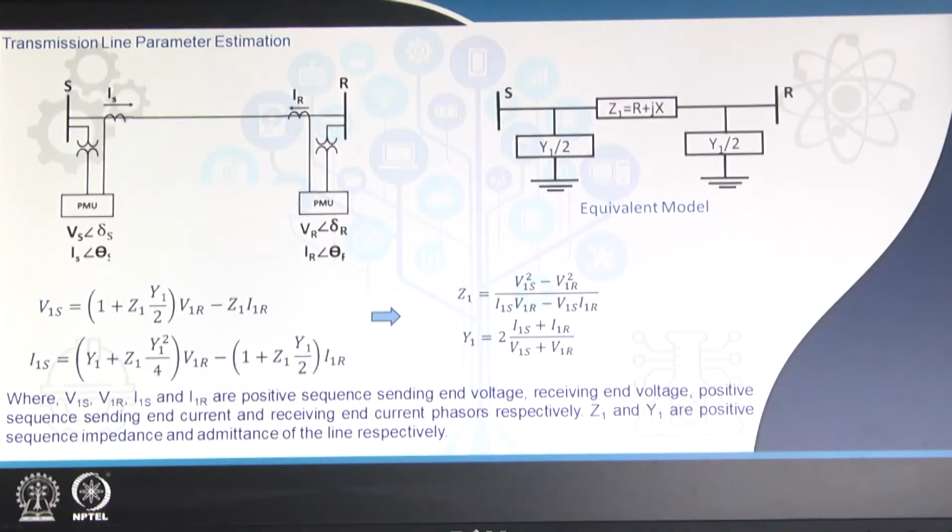So, as we have seen in these demonstrations, we can collect the data from these 2 PMUs. For this particular experimentation, to have a simple application, we have a section of line connected between PMU 1 and PMU 2. So, this line section's parameters are to be estimated. For that we collected the data of PMU 1 and PMU 2, and the theory behind this is that